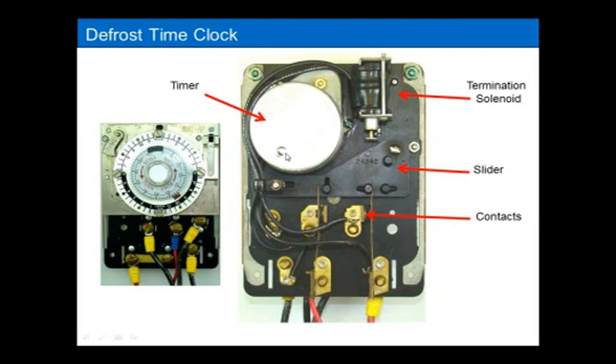You can use it as a measurement of seeing if the timer itself is not burnt out inside or if the motor itself is not defective. So it is a nice little indicator.